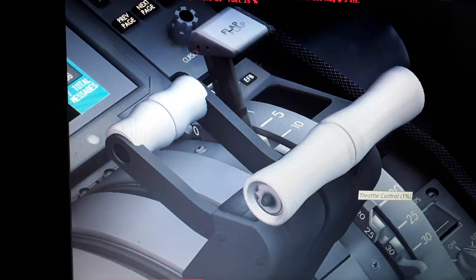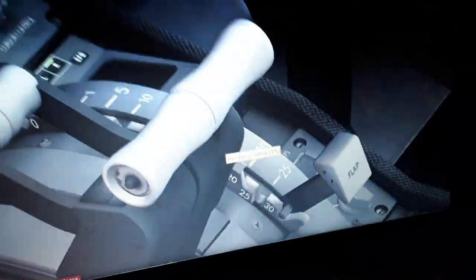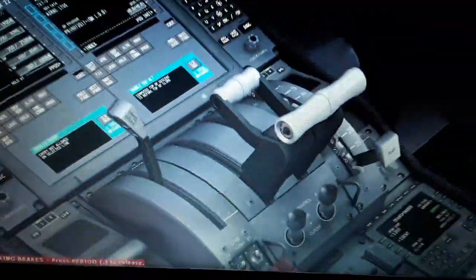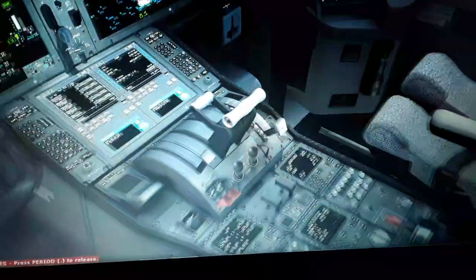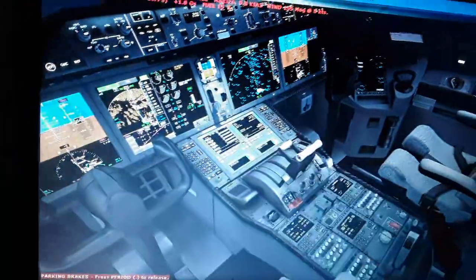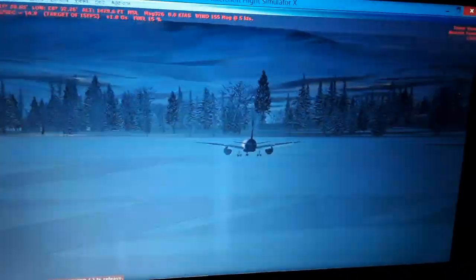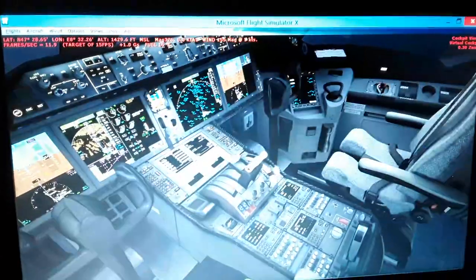So we keep retract. You can see the flaps position all the way down. We have the speed brakes also, retract and extend, the thrust lever. So you'll see the flaps over here right now are moving in transition. You can see them fully extended, and also the speed brake fully extended.